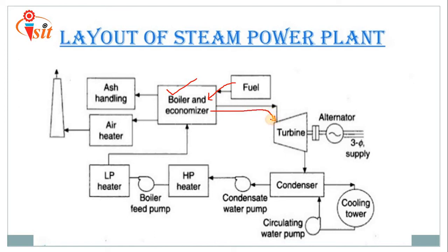Okay, so this is not another kind of turbine like hydro or gas turbine, it is a steam turbine. The blades are designed in such a manner that they can absorb the maximum energy of the steam, because whatever steam is leaving the boiler is supposed to be dry saturated. Dry saturated means its dryness fraction is 1, meaning there is no moisture content present in it. Such dry saturated steam is generally used.